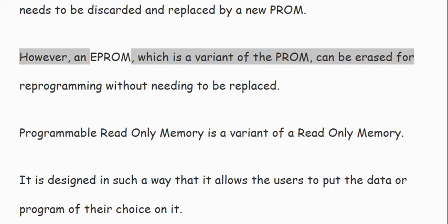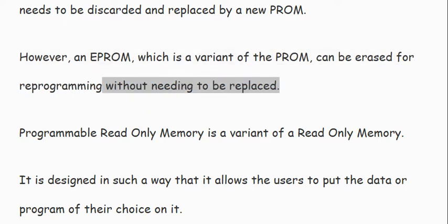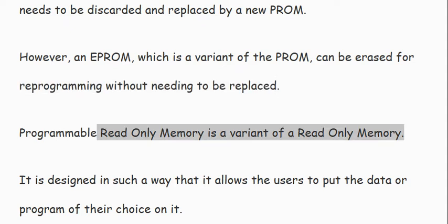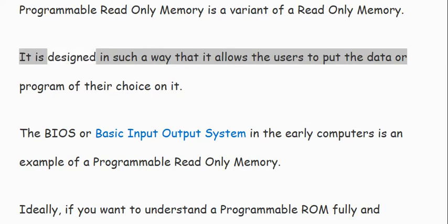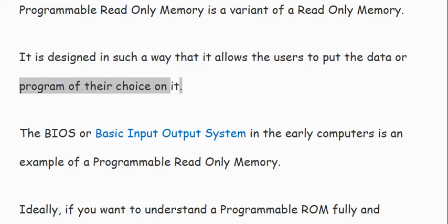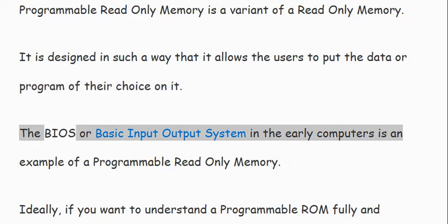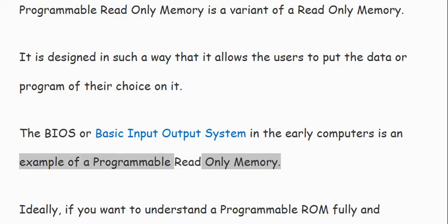However, an EPROM, which is a variant of the PROM, can be erased for reprogramming without needing to be replaced. Programmable read-only memory is a variant of a read-only memory. It is designed in such a way that it allows the users to put the data or program of their choice on it. The BIOS or Basic Input-Output System in the early computers is an example of a programmable read-only memory.